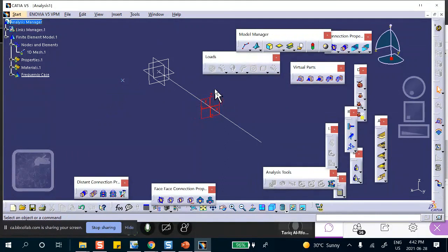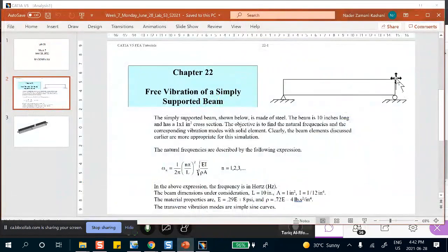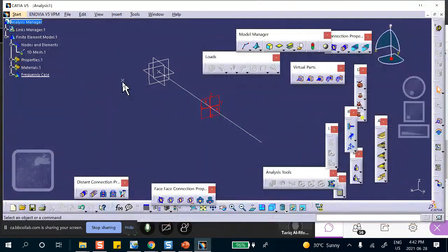Well, if you looked at what I did a minute ago, this was tilted. It was tilted. For this particular problem, I don't want it to be tilted. I want it like that, the 1 inch through the thickness of this. I don't want it tilted because the response is going to be different, okay? So the role of this orientation point is to make sure that this is oriented properly so that when you load it or you calculate frequencies, etc., it is what you want, okay?